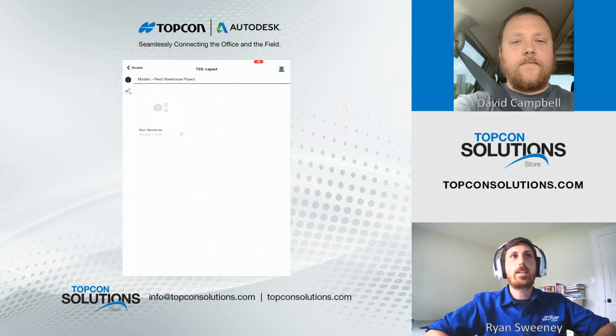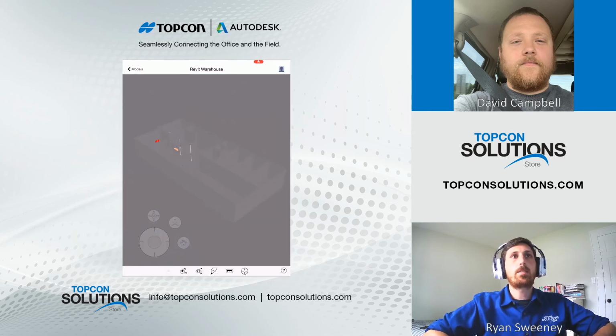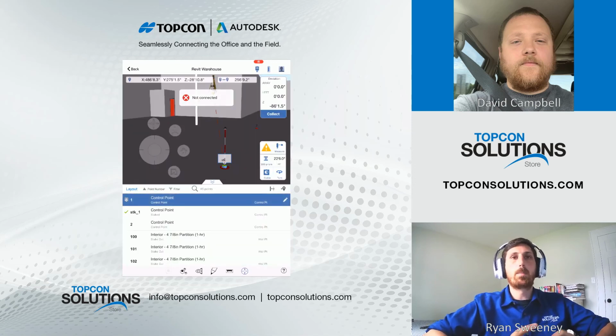So we're going to go right ahead and click right into that Revit warehouse model. It's going to load up right in BIM 360 layout. And from here is where you can start either annotating or connecting to your total station and collecting measurements. And to do that, you'll be clicking the blue or black crosshairs in the bottom right hand corner. And when you're connected to your total station, instead of not connected here, it would give you a nice green warning that says connected. And from there, you'll be able to start setting up your total station, which we'll be going into next.